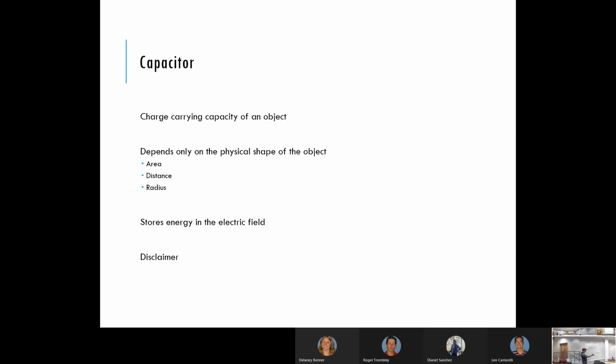So you can pull it out. It's not part of a circuit. It doesn't look dangerous anymore. But if you touch the two terminals, you're going to get a jolt. That's the scary thing I find about capacitors: they don't have to be hooked up to a circuit in order to shock you. So you usually see these disclaimers, right? Unplug device before opening it up.